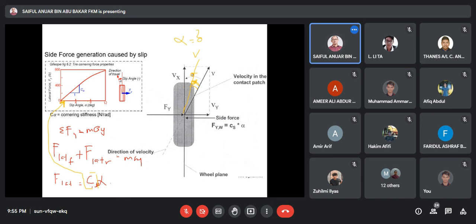So for a certain slip angle there is going to be a high lateral force. But what does it mean to have a high slip angle? Let's say this goes up to 14 degrees, so we are going to extrapolate this graph up to here. There is no such thing as a bigger slip angle of 14 or 15, because usually at that point the car will not go in the intended direction, so that is slip.